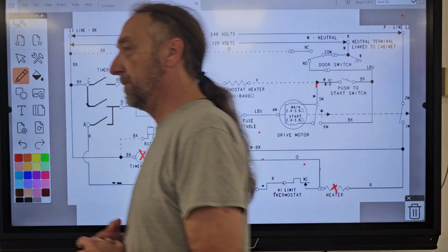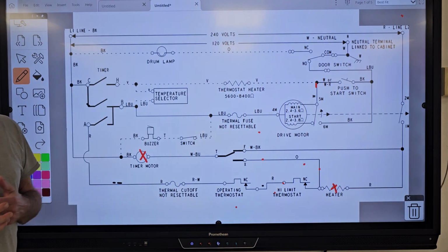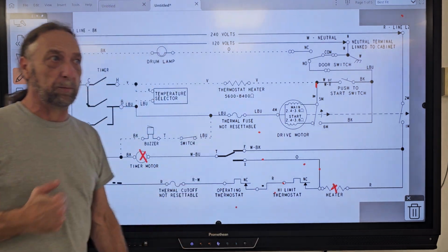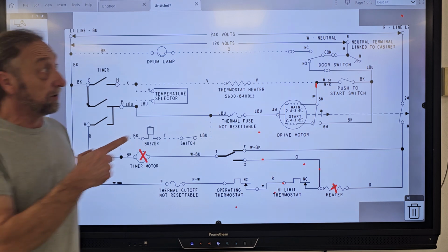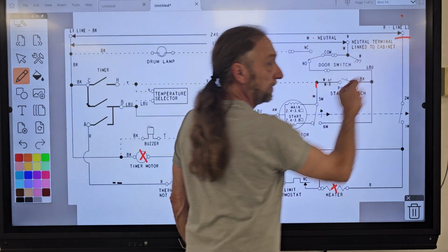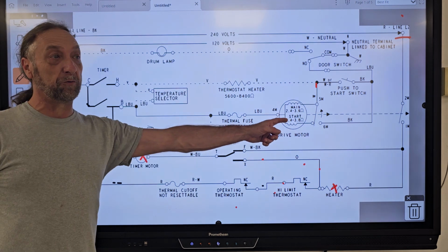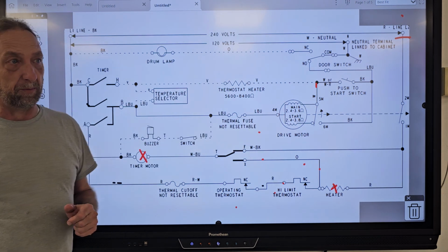Take a look at the diagram. I told you the dryer runs. No power? That would be no problem. Power? It could be the power, but specifically what power? 240. Well, specifically line 2, right? Because line 1 would stop the motor from working, right? So that's not my problem.